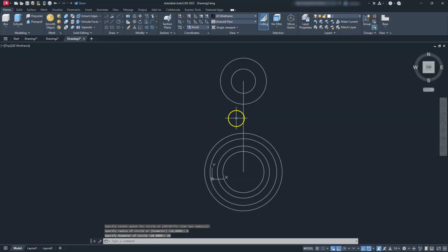All right. Lastly, I just need to put those two fillets on the outside of here. So I'm just going to type in F, enter. That F stands for fillet. R, enter. That's going to give me my radius. 64, enter. And I have multiple, so I'm just going to hit M, enter. All of this stuff can be done down here at the command line, but I'm just going to type them in just to kind of speed things up.